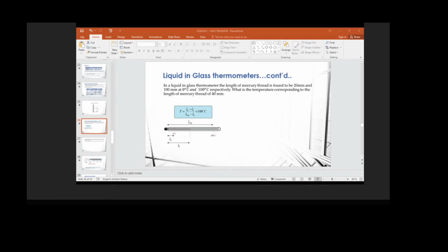So they have fast response, meaning if there's a sudden change in temperature, then it picks up that sudden change very fast. Right? So resistance to corrosion, chemicals, and oxidation, so it doesn't get corroded or oxidized very quickly. It has a wide range in temperature reading, so it can read from as low as negative 180 degrees to a maximum of 760 degrees Celsius.